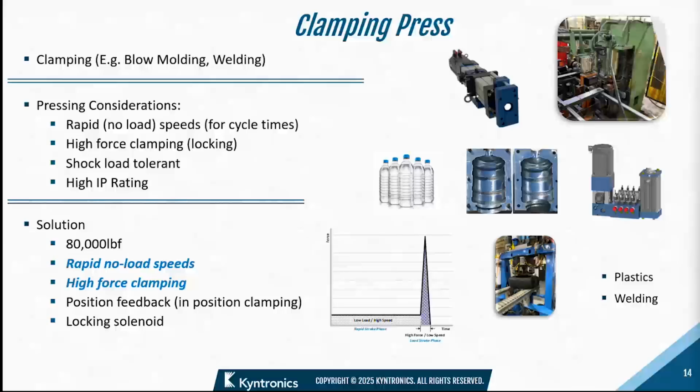Clamping is another different type of application. This one particular one is if you needed to quickly get into position and clamp. Mechanics don't like the clamping too much because you got all the clamping situation pushing against all those roller bearings and ball screws and everything else. With hydraulics, as I mentioned, it's pretty incompressible, doesn't care about the shock load, so it's really ideal for clamping.